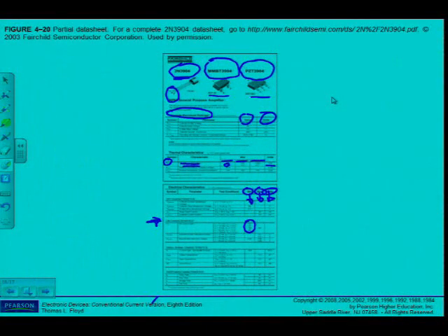Alright, so it is important that you get HFE. And you will see at the end of this chapter some of the problems they ask you in the question: determine this and this and this, and use the minimum specification or the maximum specification. Then I would go and look, what is the minimum HFE in this specific case? And I can see, alright, the smallest number here is 30, for instance. Then I will use that value.